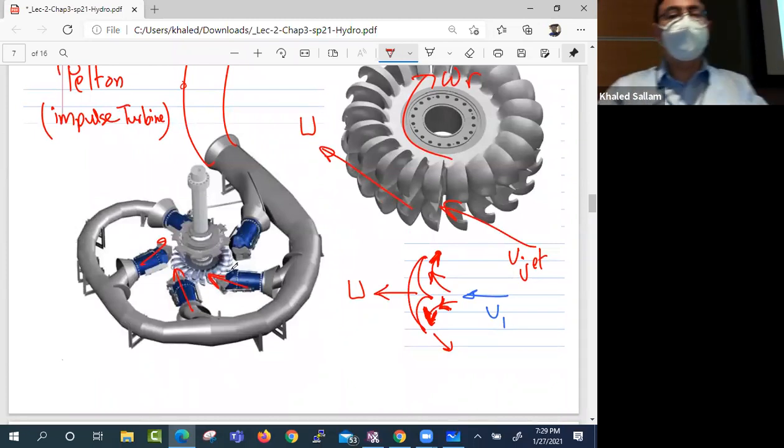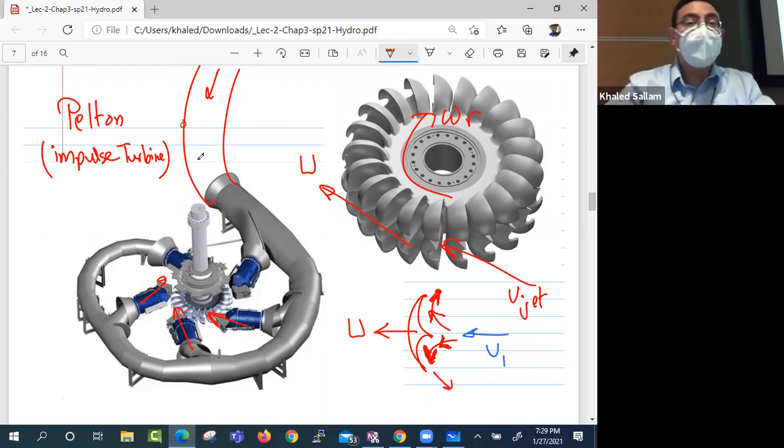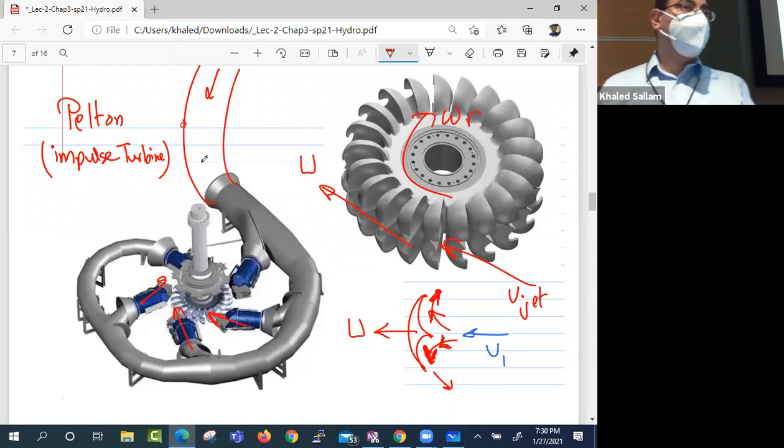Sometimes the rotation or that initial momentum is generated very easily just by, look at this. Here is the water tube coming from, say, 100 meter or whatever the elevation is. Water is rushing because of what? Because of this, right? When you drop the water from a very high height, by the time it comes down, ideally the speed should be, if I'm dropping it from H, what's the ideal velocity? No losses whatsoever. What should you get? Square root of 2gh, right? Square root of 2gh, how did I get that?